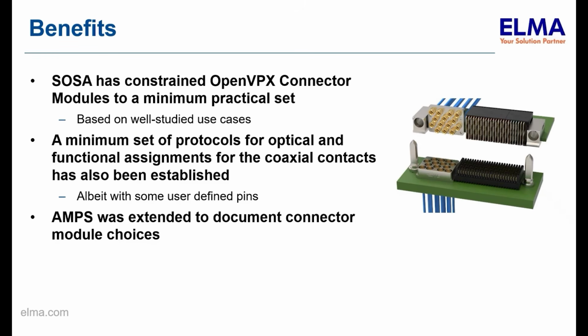What this all means is that SOSA has constrained OpenVPX connector modules to a minimum practical set based on well-studied use cases. A minimum set of protocols for optical and functional assignments for the coaxial contacts have also been established, albeit with some user-defined pins, and AMPS was extended to document connector module choices.